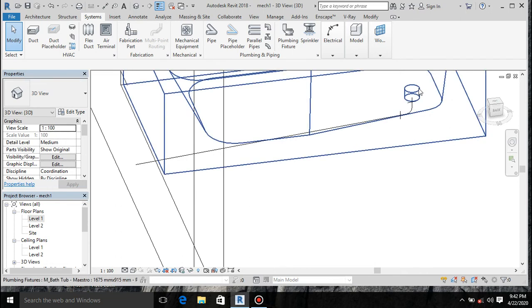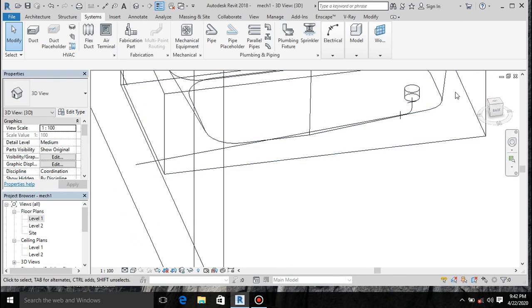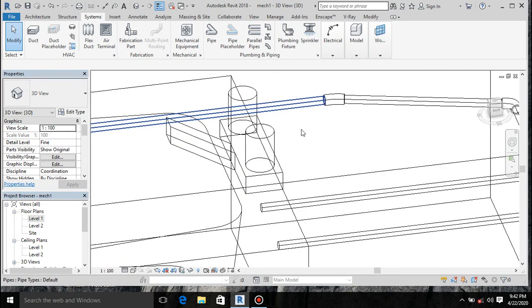You know, if you have your plumbing for the basin or for any sanitary appliance, the wastewater going out of the bathtub or the wash hand basin or anything is supposed to be at an angle, so that the flow of the water will go straight to the exchange chamber. Because if it is not at an angle, it will obviously come back into the bathtub. So that's the theory, that's the logic behind it. I really forgot about that.